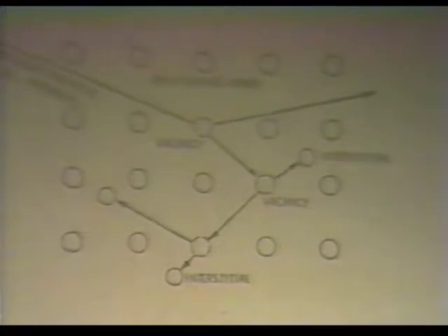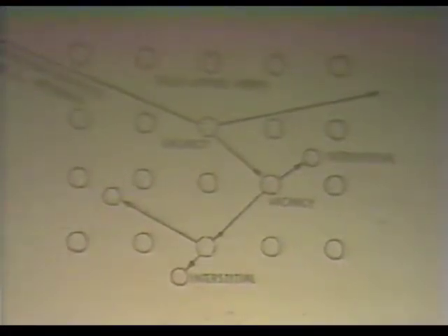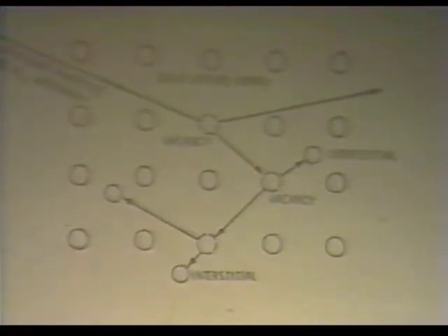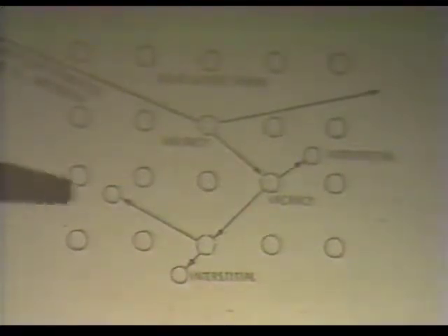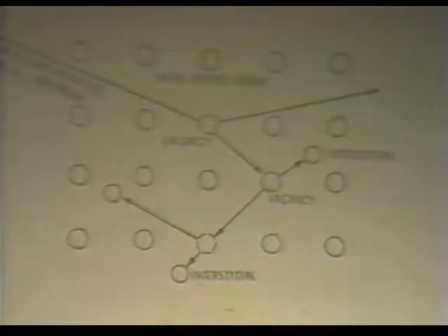Because before you dissipate all that energy, before all the pool balls come to rest, you've moved several of them. And so you end up with defect clusters in your crystal. Where you had a nice orderly arrangement, now you've got what we call vacancies and interstitials because they're out of place. A vacancy is where one ought to be and is not, and an interstitial is where one is and it ain't supposed to be.